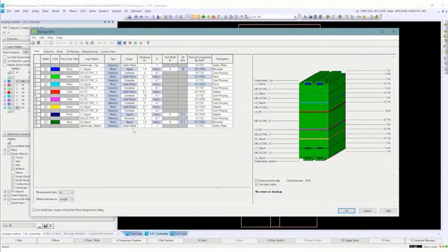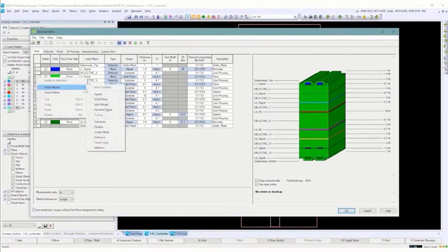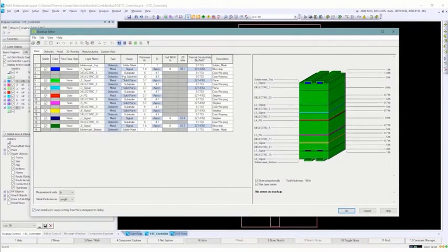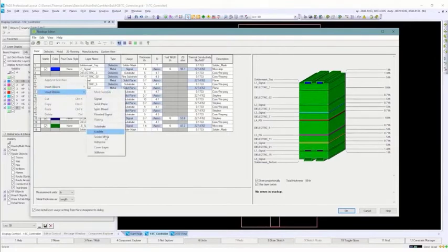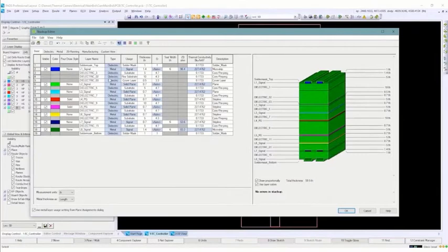So the push button board, we're going to route that out from layer 2. And it's only going to be a 2-layer board. We only need a 1-layer flex, actually. So what we need to do is add at least the 1 layer in here. Underneath the dielectric, right above layer 2, we're going to insert a flex region. And right above that, we're going to put a cover layer because we have to. That's like the solder mask, obviously, for a flex. You can add adhesive if you want, but it's so thin. It depends on the type of adhesive that you're using, and if you want to take that into account in the thickness of the board. But you can add that layer in as well.